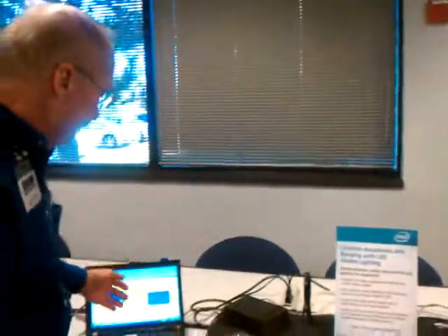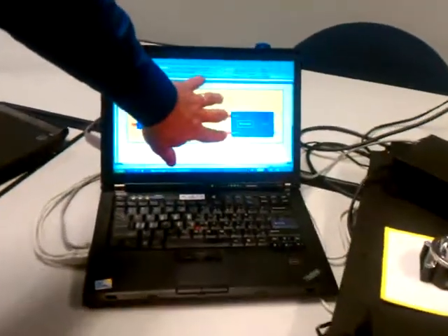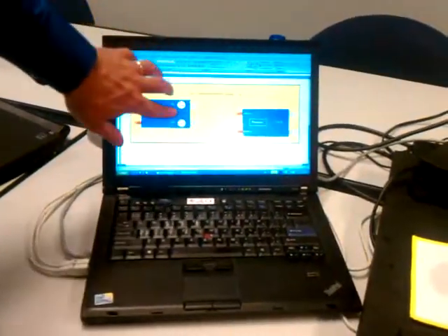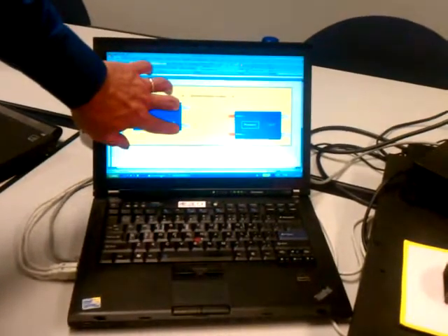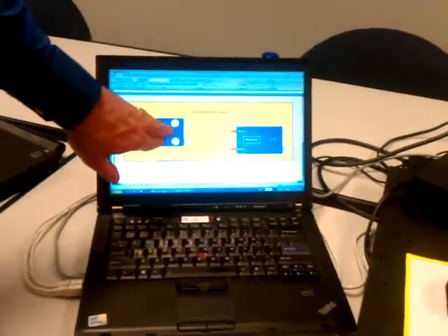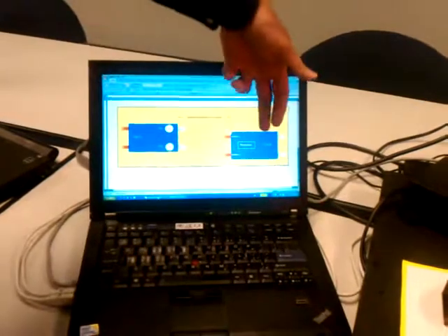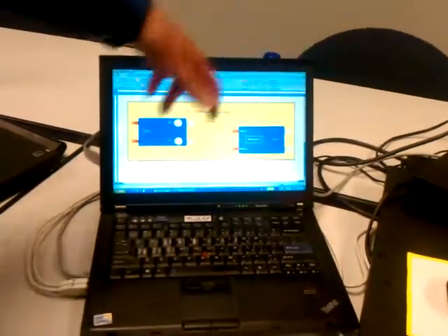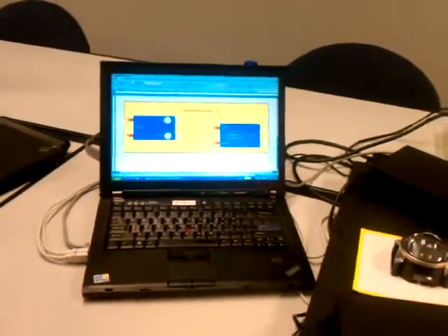And basically what it is, using the tail lights on a car, for example, with receiving sensors embedded in the front end of the car that can see these tail lights, using that information for this automobile here to determine its relative position with respect to this car here. So it can determine the two-dimensional XY position with a high degree of accuracy.